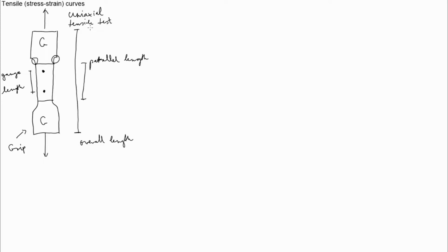So what you get from this measurement is basically two things. One is the load, expressed in newtons usually, or if you have large samples then it is in kilonewtons. In my samples I get the results in kilonewtons. And then you have displacement, which is usually in millimeters.